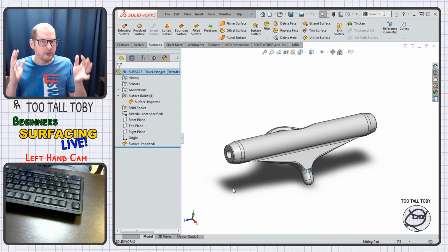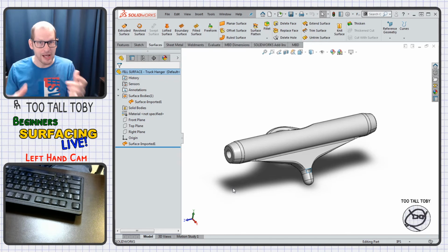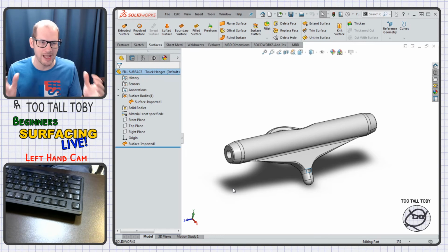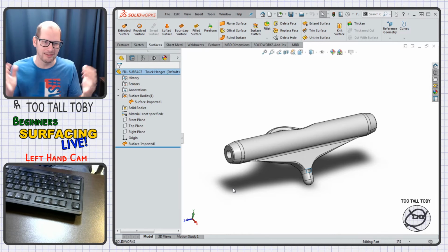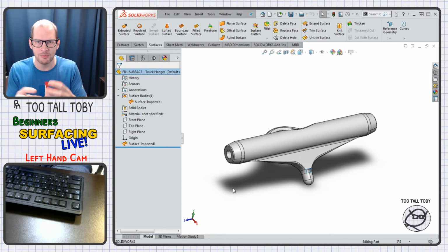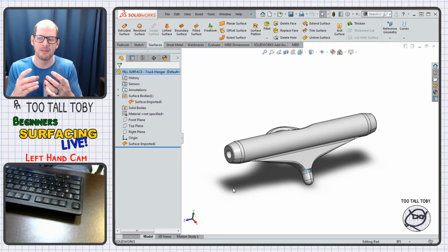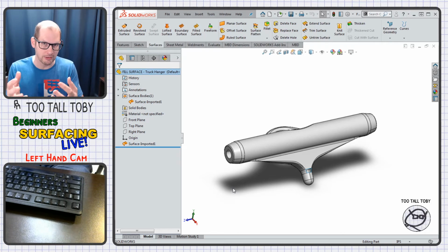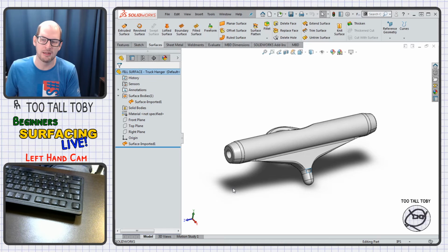Well, we want to go through the same exact workflow: create a watertight vessel and turn that watertight vessel into a solid. A bunch of people have had this. Varun, you've had this before. Avery, you've had this. Rashab, you've had this. Stefan, yeah. Chuck, you've had this before. Sandy, yeah, you guys have all had this. So you want to take this surface model and turn it into a watertight vessel, and after it's a watertight surface, you want to thicken it into a solid.